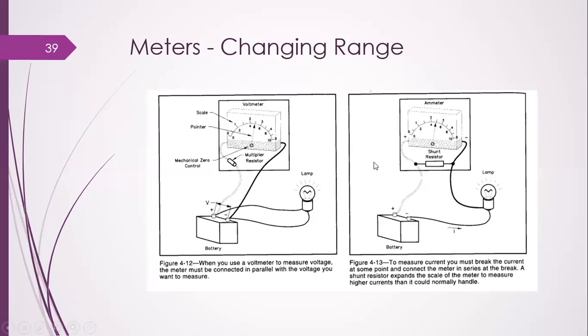Then this is the way. So if we connect a galvanometer to the shunt resistance, which is a low resistance, in a parallel connection, then that galvanometer would be named an ammeter. So this is how to transform a galvanometer into an ammeter.